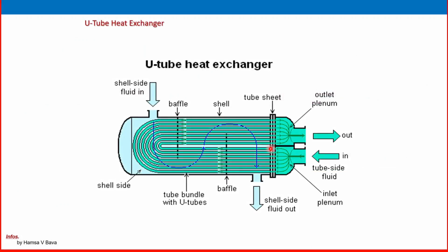And this is one of the U-tube type shell and tube heat exchangers. You can see, just have a look at that one. One side it is a U-tube. The flow is entering and coming to this side and going back to this side. So it is a two pass, two flow. See, and the U-tube bundle of tubes is arranged inside the shell in such a way that you can remove it for cleaning purposes. We will study details in our coming slides. Advantage of U-tube type heat exchanger.